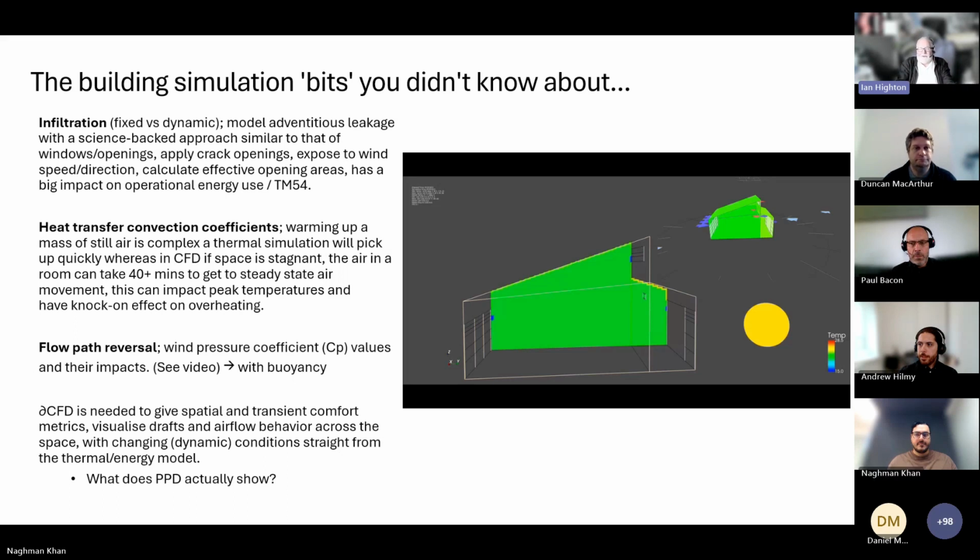So the regulations are fine, they've got to do something. But a big difference between the real world and what we do as far as the regulatory calculations is flat infiltration versus calculated infiltration. And obviously the calculated infiltration is based on cracks.